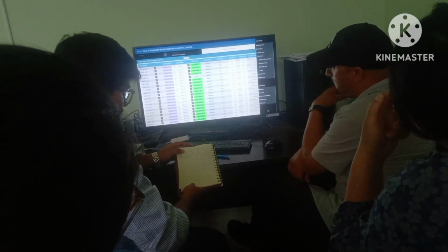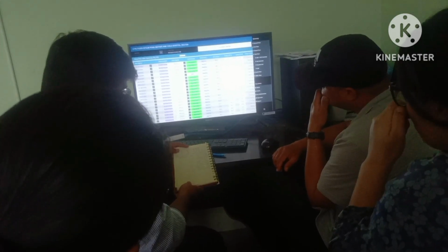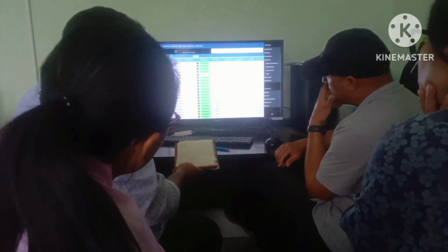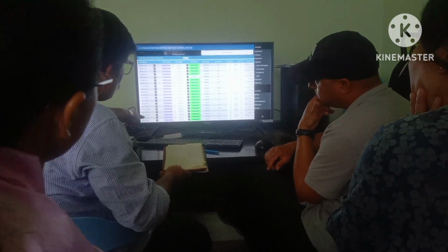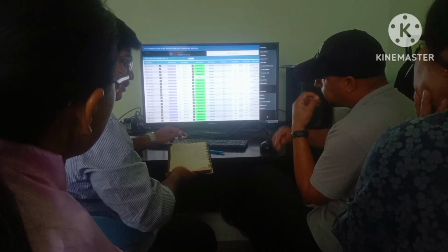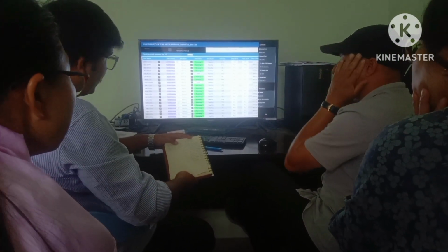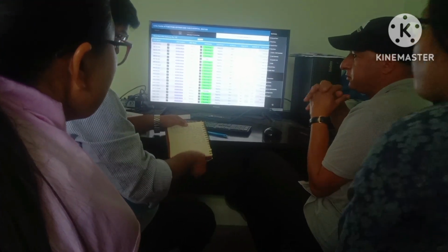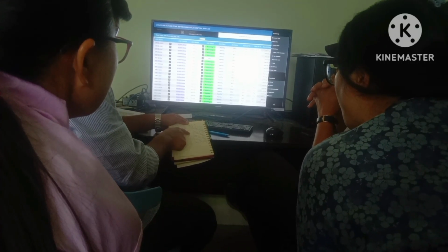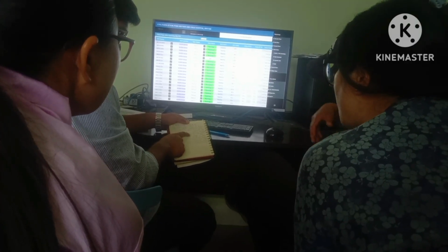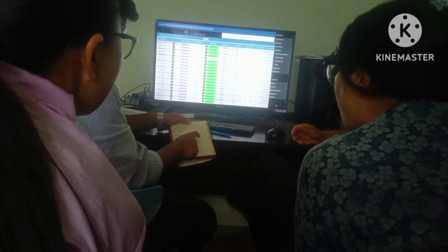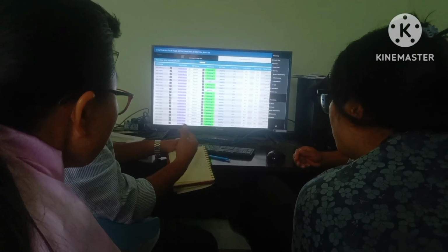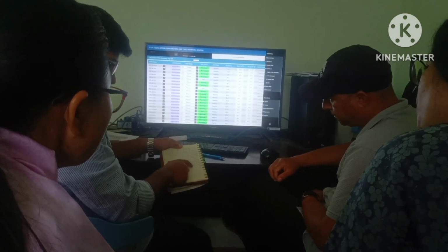Position number. Then there is a dash and in between a letter. That letter indicates the block: B block, then C block, and then there will be a D block. Then the rest three letters indicate what type of device it is. If it is AHU, then air handling unit. CSU, then ceiling suspended unit. SF means supply fan, which is basically a fresh air fan. EF stands for exhaust fan, which is basically a ventilation fan. And C stands for cassette unit.